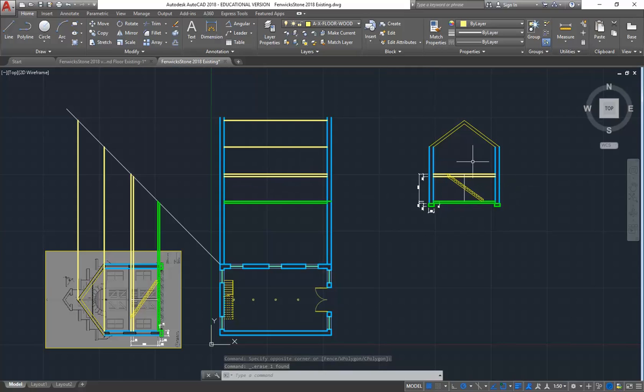If you've got more detailed things to project, sometimes it's a bit tedious drawing everything to this 45-degree line. So there's nothing wrong with projecting across this way. It's just that if you change this other section, you'd need to copy it again and rotate it again. But those methods definitely work. Some people will go a bit further and use what are called XREFs to link one file to another. I think that just creates too much work. For a simple project like this, you shouldn't need XREFs at all, really. But we'll have a look at those things later anyway.